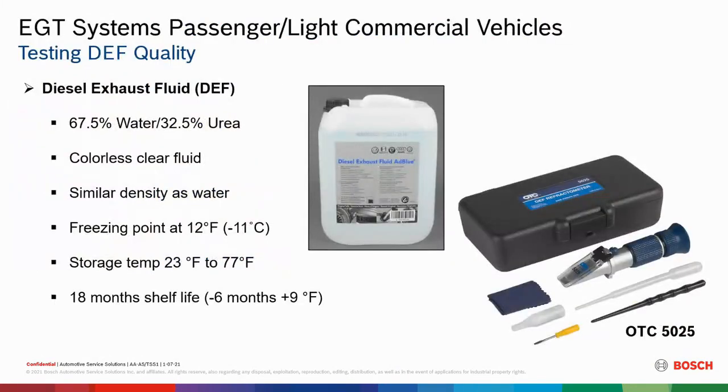So now let's talk a little bit about the DEF fluid in the exhaust. I don't know why they put the name diesel exhaust fluid on here, or the name diesel, because some of these fill tubes are right next to the diesel fuel. It's a constant battle. A brand new truck recently came through on our help desk line, a brand new Cummins application, where somebody put DEF fluid in the fuel tank and destroyed the whole system. It's going to be thousands of dollars to replace this system.